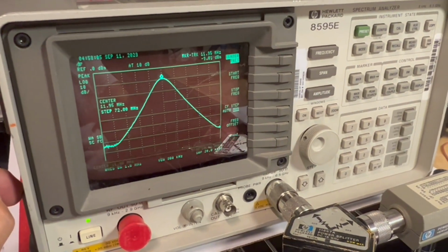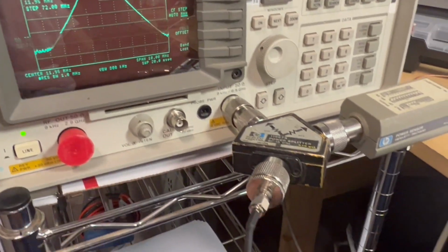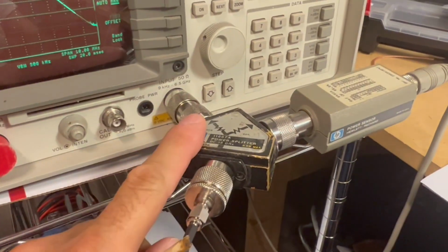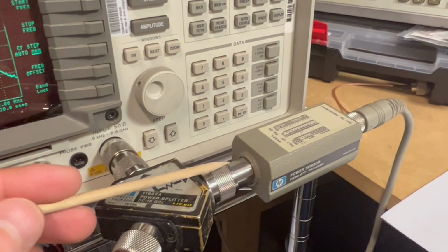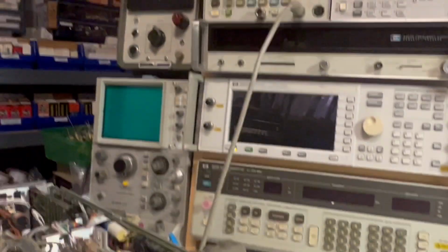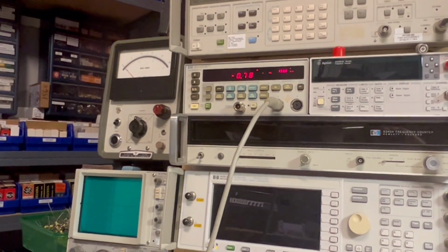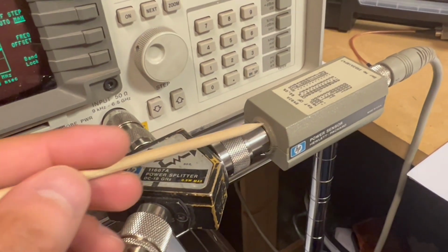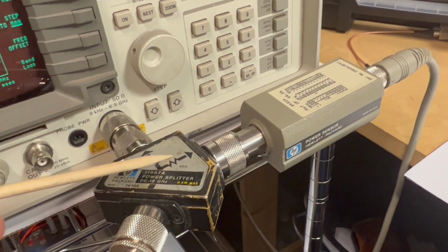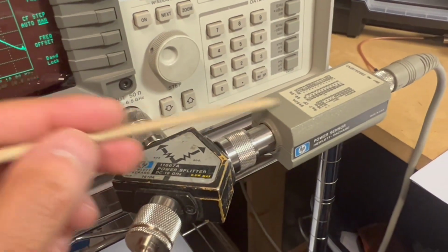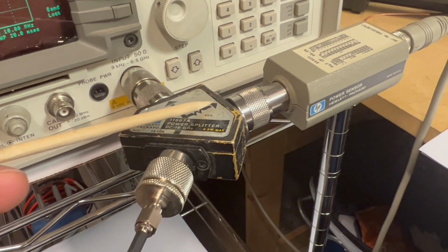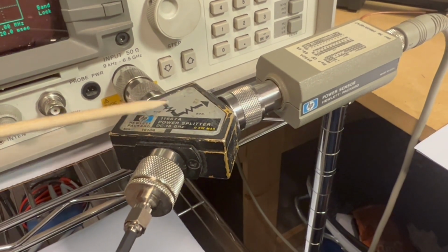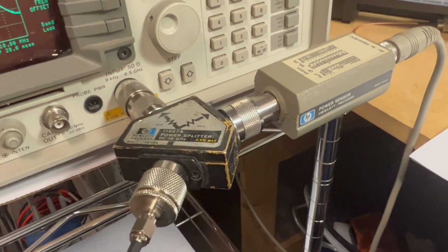So here's my setup right now. I've got the spectrum analyzer already set up per the procedure, and I'm feeding the signal in from this cable to a power splitter, and on one side we're going into the spectrum analyzer, the other side we're going to a power sensor, and that's going up to my power meter up there on the rack. Off the power splitter we have two very close points of reference for the spectrum analyzer and the power sensor, and this power sensor's matched pretty well for the split power, so it's sending power equally to both ports.